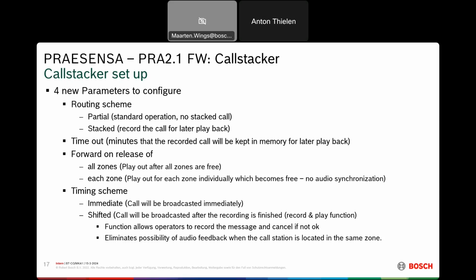For all zones, that means that the audio is only being played after all zones are free. That also avoids, for example, when you have adjacent zones, that in one zone it is played already, and then the other one will play a couple of seconds later. That will influence your intelligibility, because they will interfere with each other. So in that case it's better to say I want to forward on release when all zones are available again. But you could also think of each zone, where you say, I don't want to wait for particular zones until everything is free.